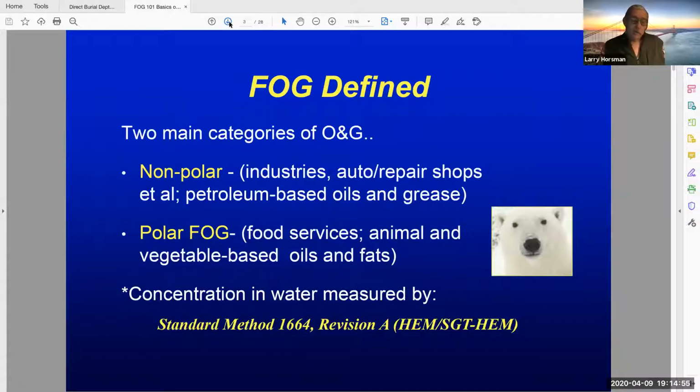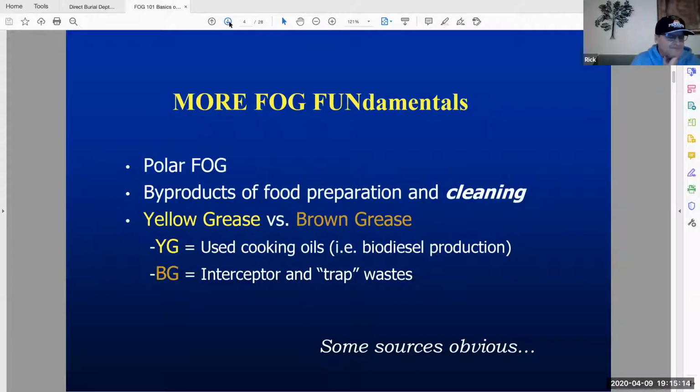If you're doing a restaurant, normally you have to put in a grease interceptor or some sort of gravity interceptor to take the FOG out of the waste stream before it gets into the public sewer. The dump out traps are for you. Some of the newer ones, they call the service company.